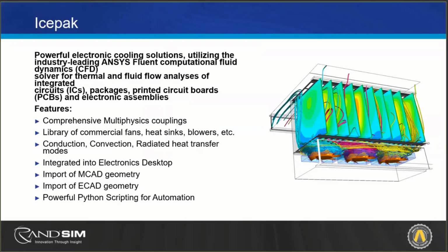This is within Icepak. It's not just the image showing here, which is a system, but you can get all the way down to trace level, to pad level, and simulate from there. Multi-layer boards, the properties within those, so importing ECAD geometry in, the thickness of your boards all get brought in as well in a very streamlined method.